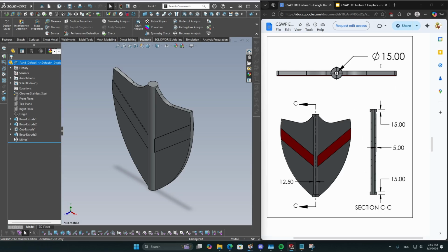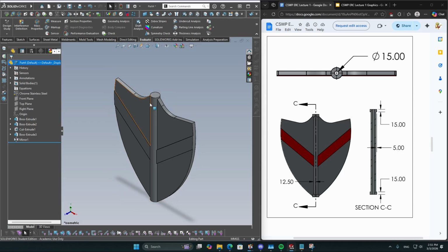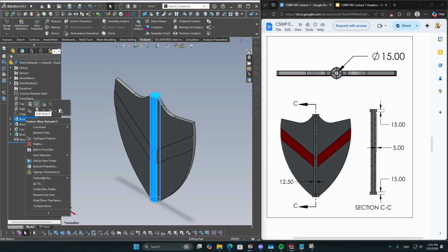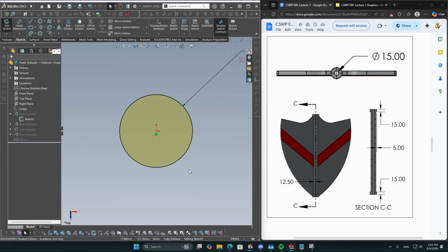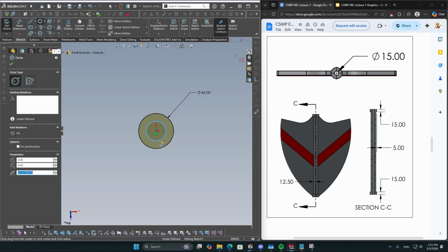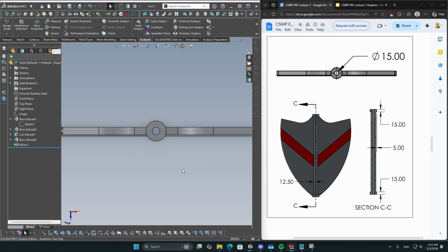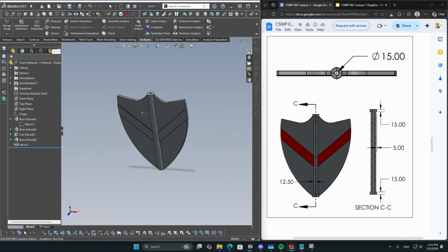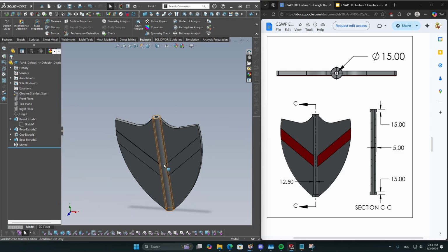that you can see from the top view and in this section view here. You could come in and add a cut straight down, but instead I'm going to use my features smartly, and just edit the sketch that this boss extrude was from. Then I'll add a circle here to the diameter that I want, which is 15. If I exit my sketch, you can see SolidWorks is a smart little cookie, so it decided to add the hole all the way through, just like that.